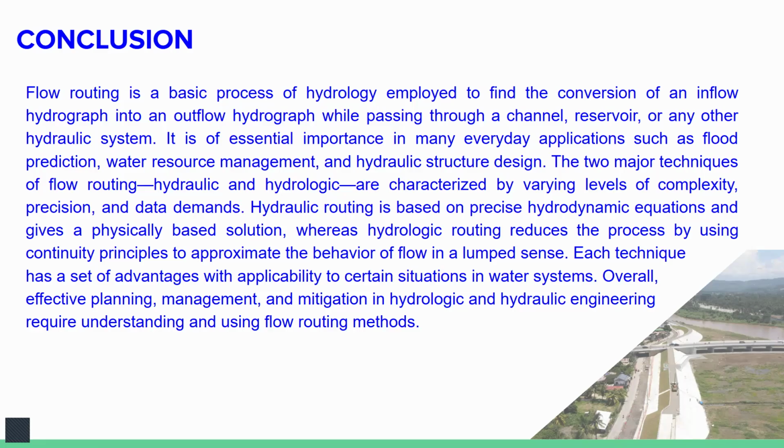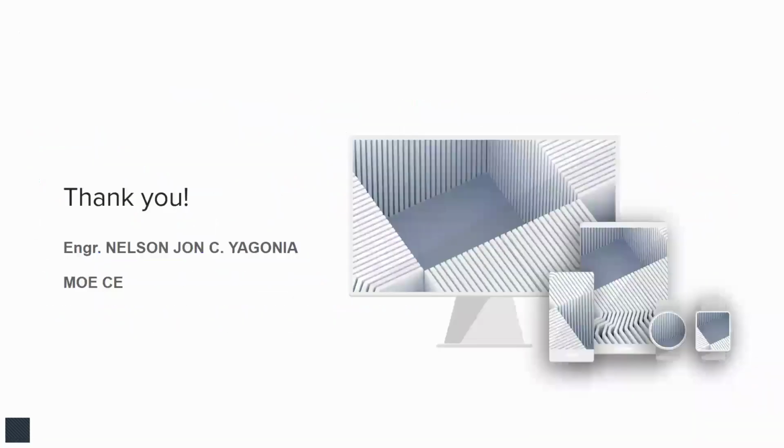Hydraulic routing is based on precise hydrodynamic equations and gives a physically based solution, whereas hydrologic routing simplifies the process by using continuity principles to approximate the behavior of flow in a broad sense. Each technique has a set of advantages with applicability to certain situations in water systems. Overall, effective planning, management, and mitigation in hydrologic and hydraulic engineering require understanding and using flow routing methods.